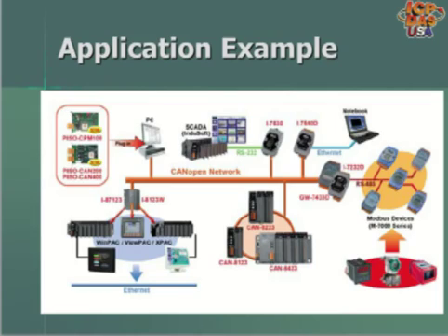I-7530 provides conversion of RS-232 to CAN, so CAN devices can communicate to PAC controllers running SCADA software. I-7540D converts CAN to Ethernet, so laptops can communicate back to CAN networks. RS-485 to CAN converters like GW7433D allow for incorporation of RS-485 devices into CAN networks.